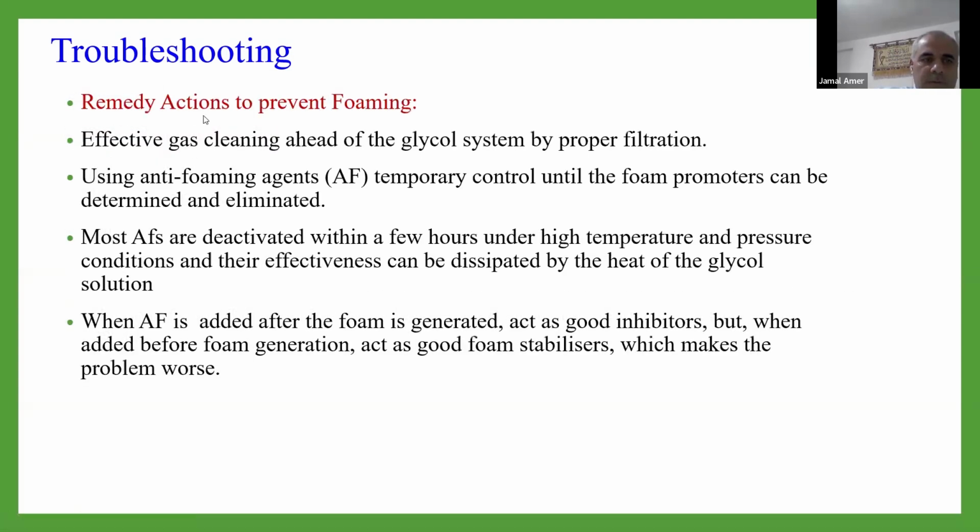So here we clean with a filter system and use anti-foam agents. This anti-foam should not be used continuously. It should only be temporary usage until the problem is solved, because anti-foam is not a continuous solution.